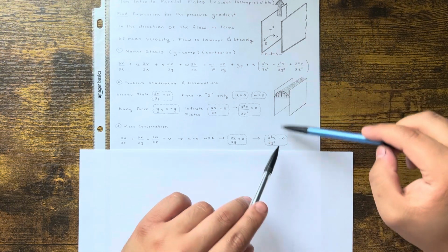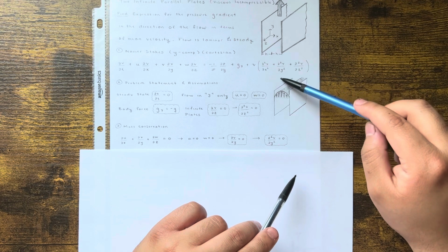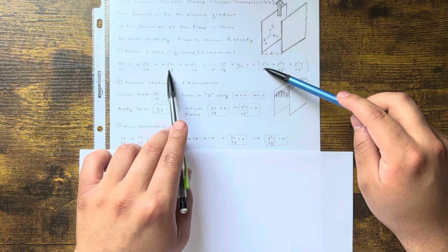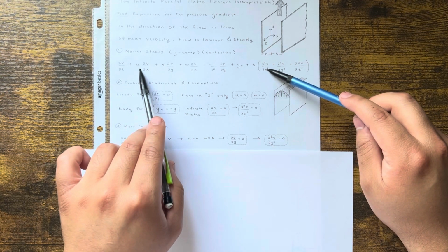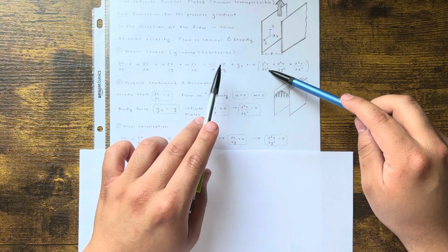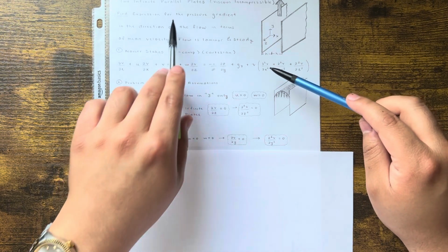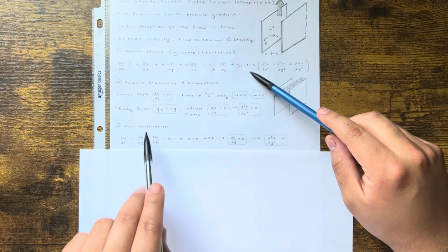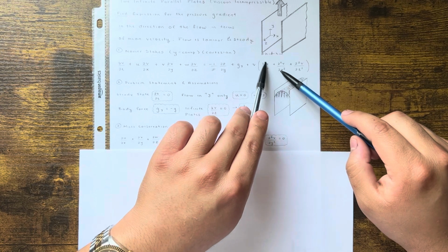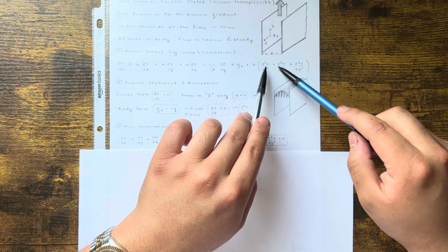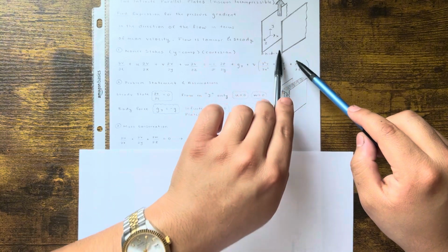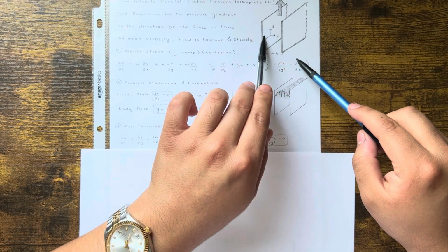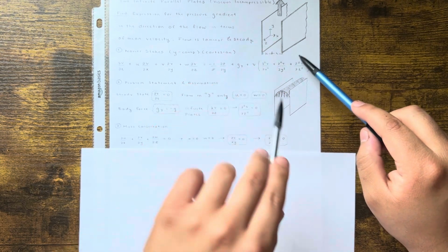Okay, so now v over y squared, that's that one right here. This went away. So now we're left with this one, delta v over delta y. That term goes away. So now this went away, this went away, this went away, this went away. So far we still have this, and it makes sense, right? That's what we're solving for, the pressure gradient. We're solving for this term right here. Gy became negative g. And then we're just down to this term. And it makes sense, right? It's telling you how does the y velocity change with respect to x. So it could be very small here, very high here, as you can kind of see.